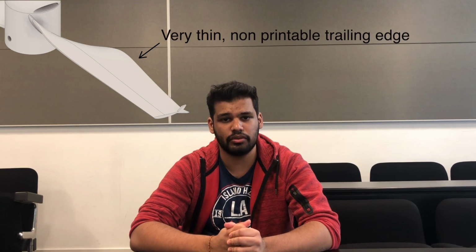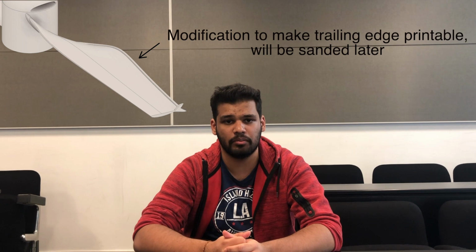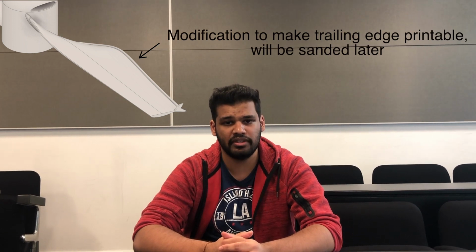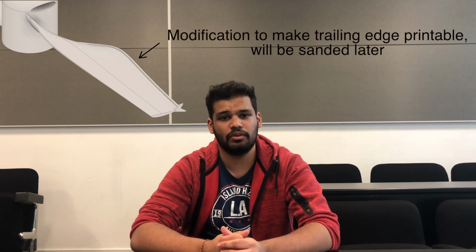To further optimize the turbine, as well as add a personal touch to it, we decided to create a channel section inside the nose cone that should help deflect the flow towards the blades. Additionally, winglets were added to reduce induced drag at the blade tips. As the trailing edge of the airfoil was too thin, a circular shape was also added to the trailing edge of the blades to ensure proper printing and also to ease the sanding process. And our design was done. Now let's make this thing.